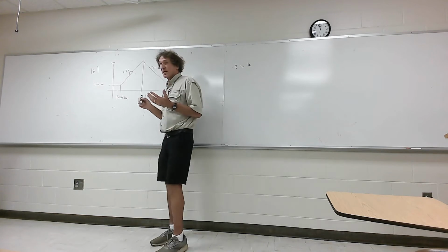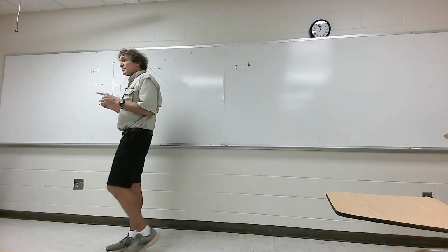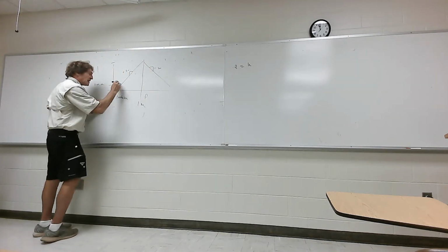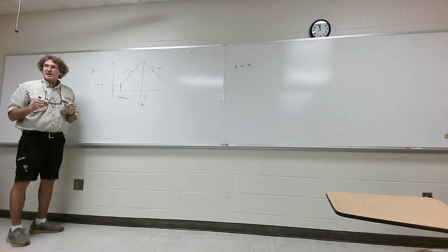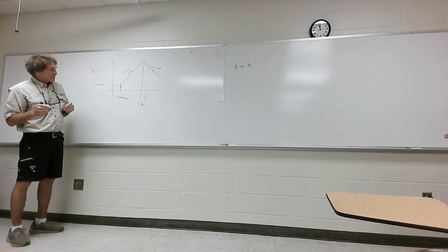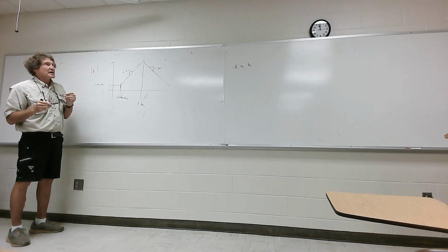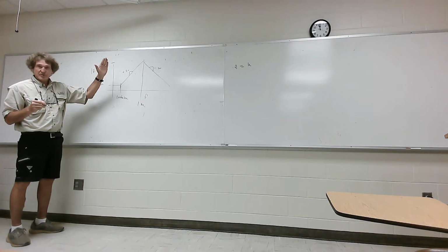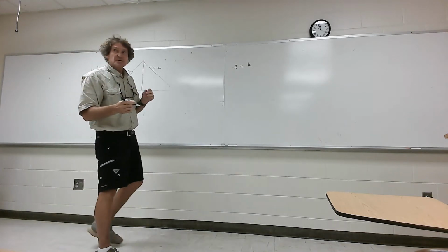We don't know what that value is. Now, here's where the important parts are. At this frequency, sorry, this is going to be a zero, it's going to start going up at 20 dB per decade, y'all follow?